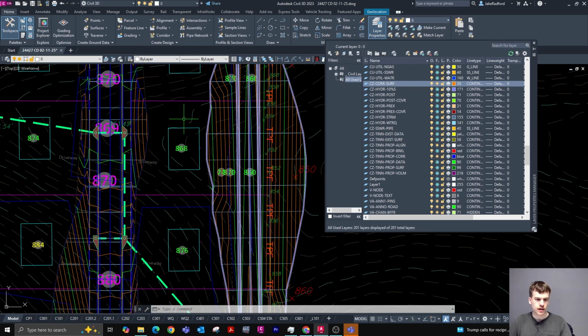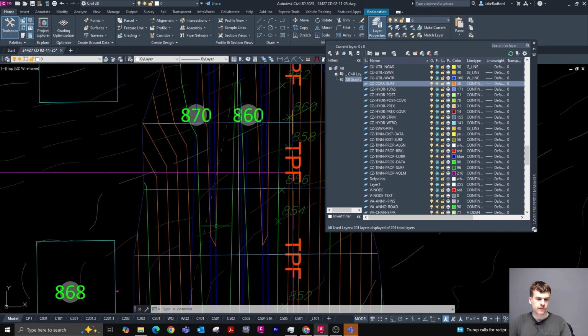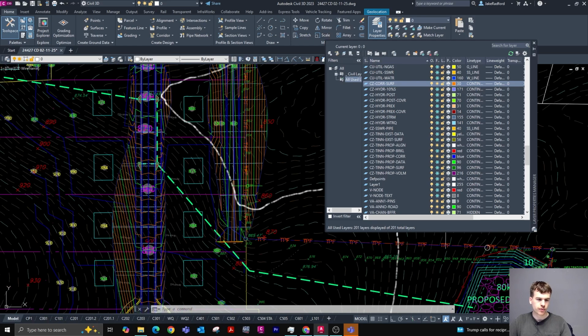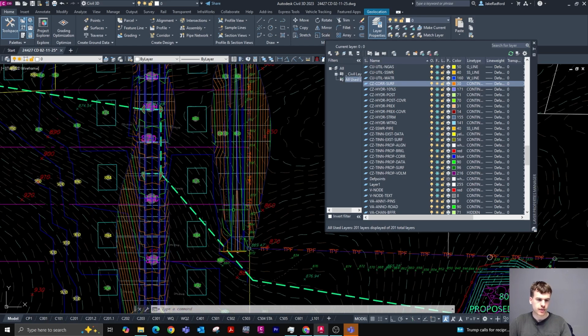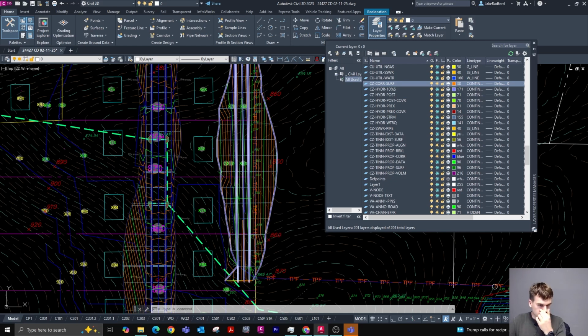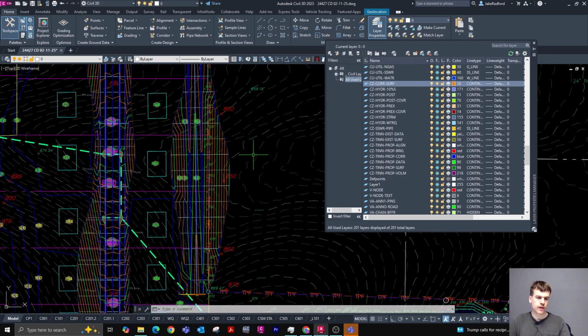But as you can see, the rest of it follows these contours. It has graded this at 1% and tied it into the rest of the landscape and graded in our swale. So this swale happens to be running perpendicular to the natural path, flow of water, which is why the grading extents are so wide. Perhaps there might have been a better location to show off the capability.